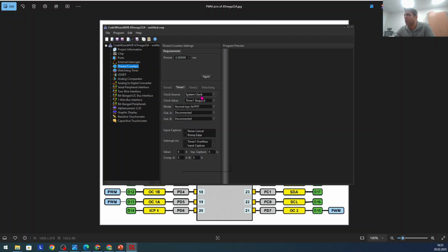In this one, let's select the system clock as the source. Let's see what options there are, like T1 pin falling edge and rising edge. This is if you want an external clock as the source of the timer, you can connect to this T1 pin. But we just want the system clock as a source. And the frequency, as I remember, it was 31.